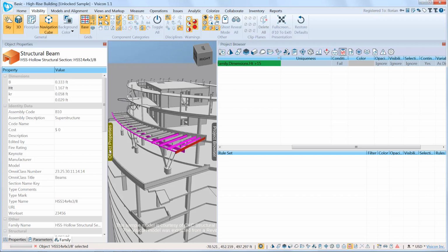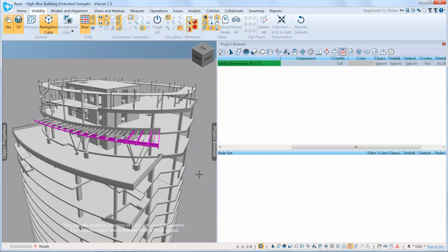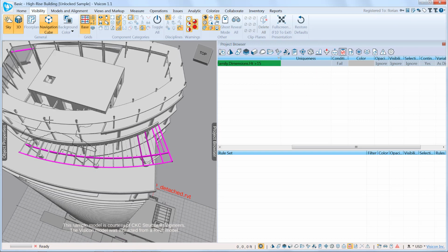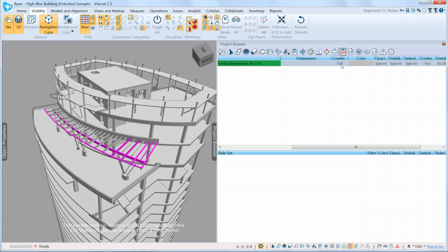Can you see how, when I turn this off, these are all the beams that, and actually there's a beam on the back side there also, these are all the beams that meet this criteria of having a length over depth greater than 15. I can simply make this 10. Obviously, it increases the number of beams that apply. So that's an example of how you can quickly write an expression and a rule that draw on different object properties, and we're using a more complex relationship between them.